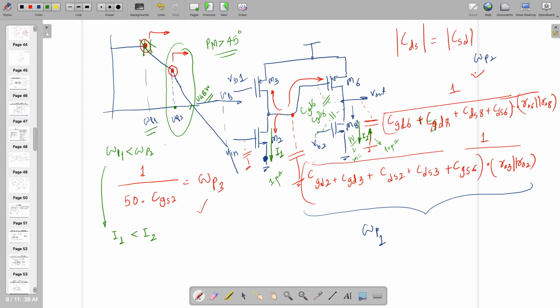But if you keep both of them at 1 micro, both the poles are here by the way, right? Then what should be the phase margin in that case? If both the poles are here with minus 40 dB per decade, what will be the phase margin? Somebody give the correct answer. Yes, Shubham. 0 degree, right?